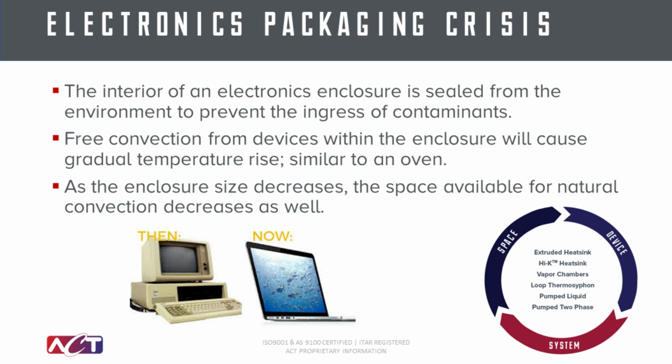Now, as package design engineers, you're typically being pushed to decrease the size of the enclosure in an effort to reduce weight or to make it package better into your next level assembly. What you're doing essentially now is reducing the space for that natural convection. You can think of laptop computers now versus the counterparts multiple years ago, where you had a lot larger devices, but smaller power loads.